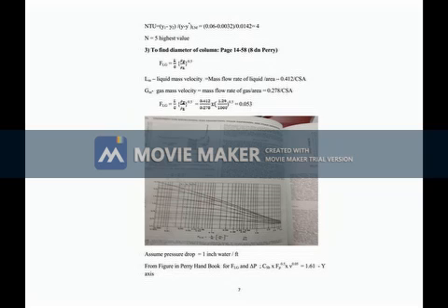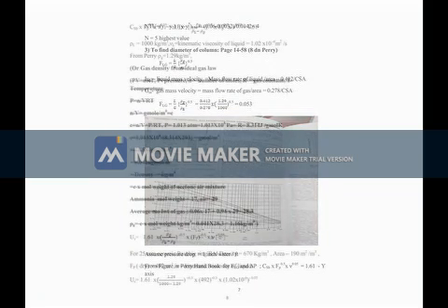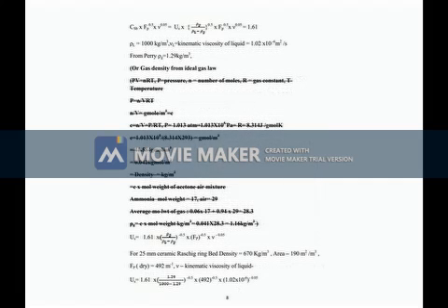But here you have to find the mole ratio, not the mole fraction. So you have to convert; capital Y1 is to be found out. Capital Y1 is equal to small y1 by 1 minus y1, that is 0.06 divided by 1 minus 0.06, which is 0.0638. Not much different, because this concentration is very low. At low concentration, mole fraction and mole ratio will be more or less the same. So ammonia to be removed is 95% of the inlet.